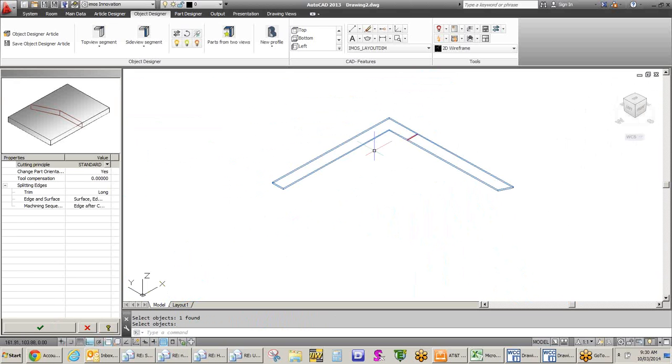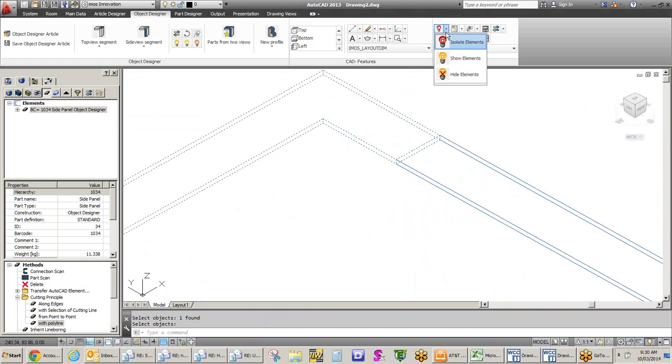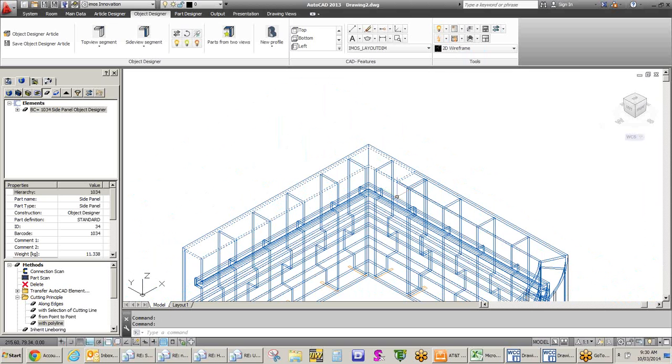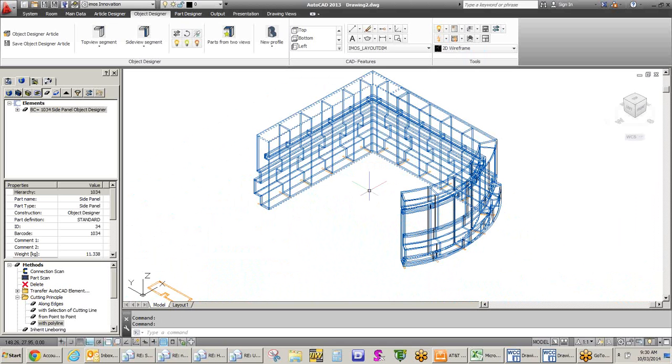And it didn't have to be straight. It could have been, like you say, any kind of shape that you might want to cut it. But now I've got these back into two objects that are broken in this case. And of course, I'd want to move these studs appropriately for it. But the same kind of control, I can make sure my bottom plates break different than my top plates and skins and all those kind of things. So I really have a tool that I can take to manufacturing.